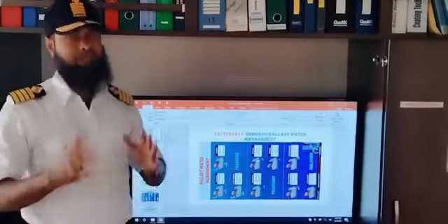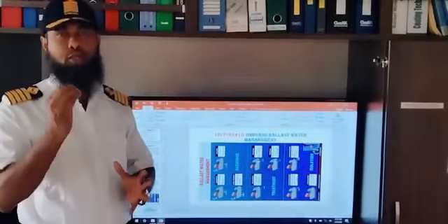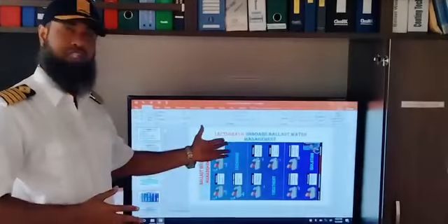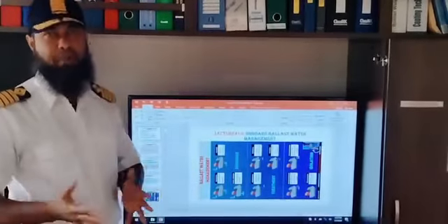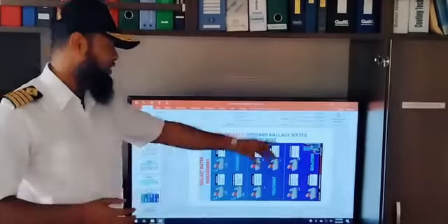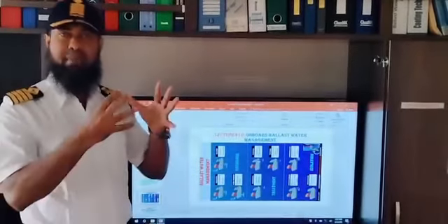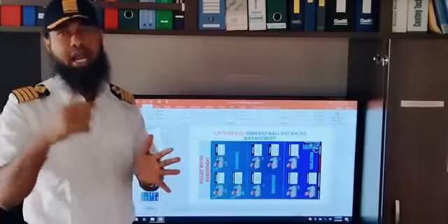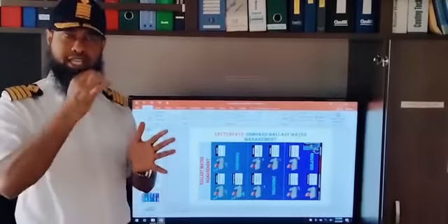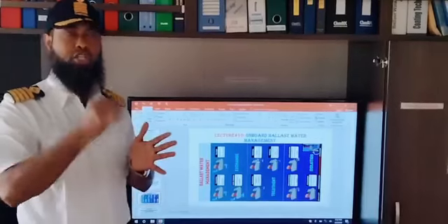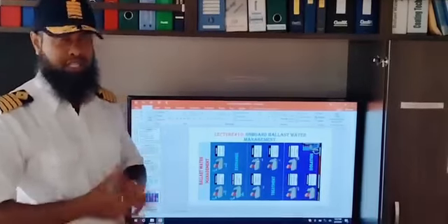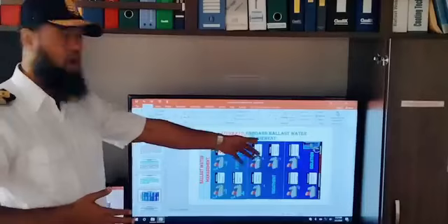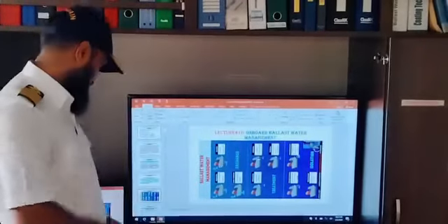But at present, worldwide almost all the vessels are using the treatment system for taking in or pumping out the ballast water. And isolation means whenever a vessel takes ballast water, she will not discharge that water in other places. Either she will keep it on board the ship or she will dispose of the ballast water to a shore facility, which belongs to the isolation method.